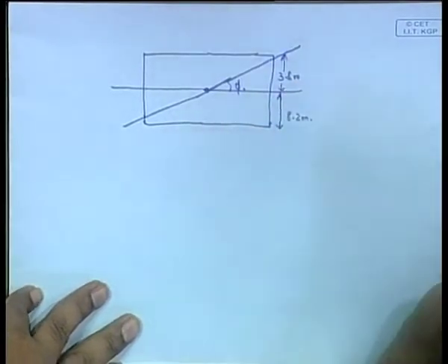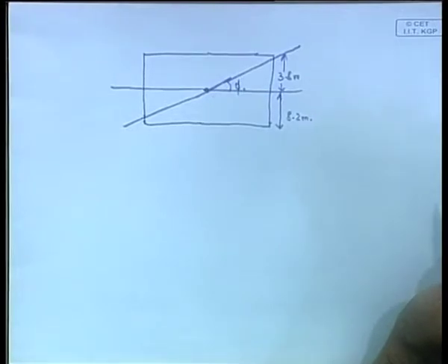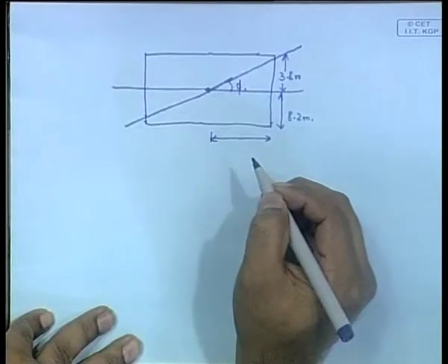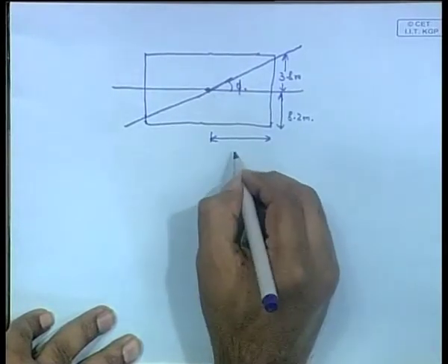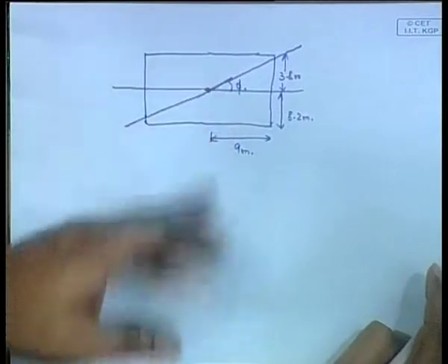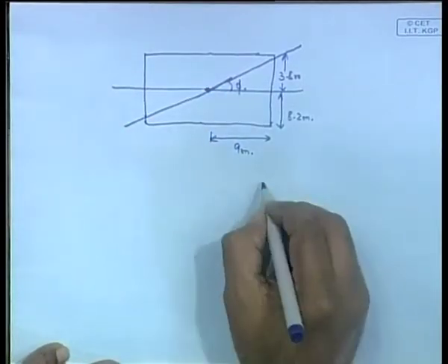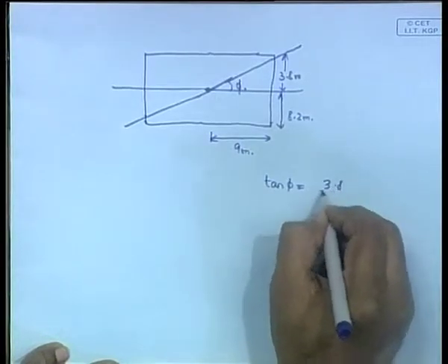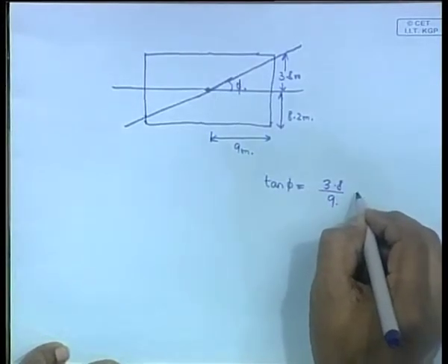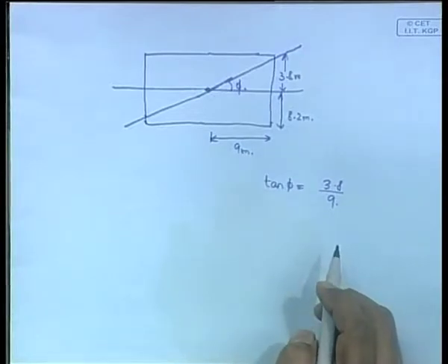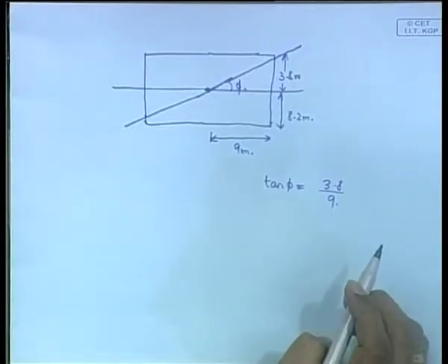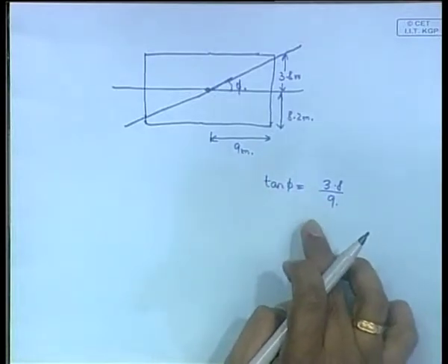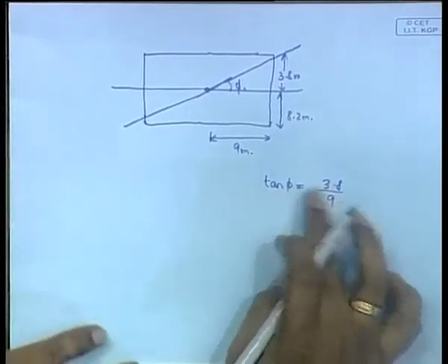Okay. Now, it is not difficult, right. And this is your b by 2. B by 2, breadth is given as 18 meters, so this is 9 meters. So, it is now very easy to calculate the deck edge immersion. You can see that tan phi is equal to 3.8 divided by 9, that is all. So, that will give you your angle of deck edge immersion. Your question is to find the dynamical stability up to the angle of deck edge immersion. So, right now you have calculated your deck edge immersion, that is your first thing.